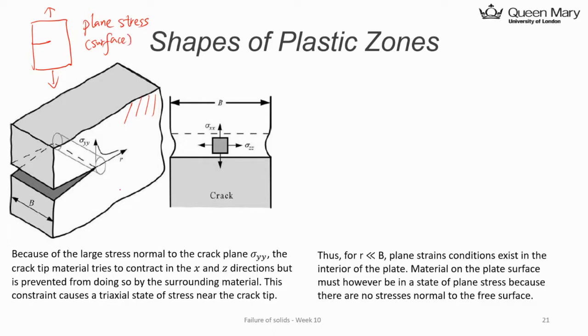How about if you look at a 3D problem? If you look at a region inside the material, through the thickness, some area like here, it should be a dashed line, somewhere like this. You cut a cross section from here, and then you view from the top. So your eye is here, and you look down, and you get this view. Now you can see the stress in this view. You need to think about the out-of-plane stress, sigma zz. And sigma xx is the stress along this direction, x. And sigma y is the stress loading in that direction, which we can't see in this cross-section view.